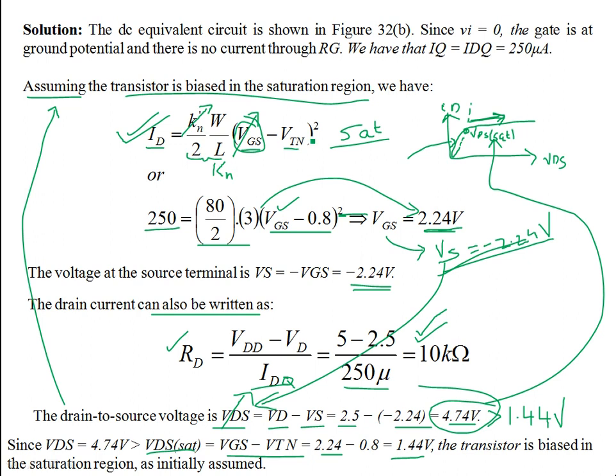In the saturation region, we don't need to bother about ID. ID is not going to vary, it's constant. For a given VGS, you have defined the enhanced inversion layer, so there is no change with regards to VDS.